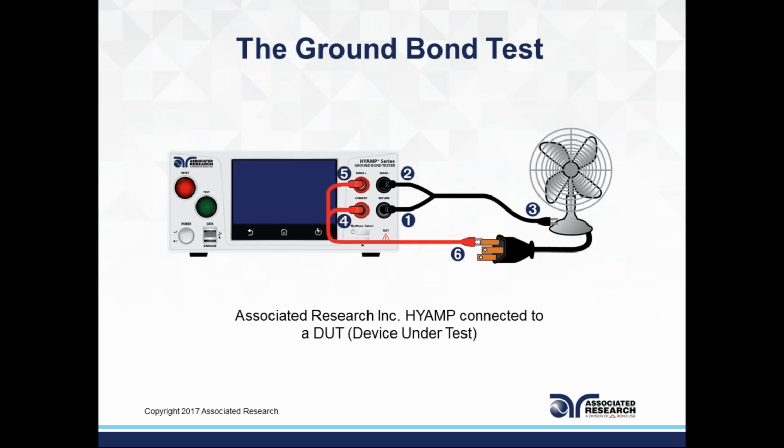The point here is that this makes a 4-wire connection, and I'll go into details when I show you the circuit diagram. But when we're measuring such a low resistive circuit, we're measuring 0.1 ohms, and we're outputting 40 or 50 or 60 amps of current. To be able to measure down to 0.1 ohm accurately, you could use a method called the Kelvin method.